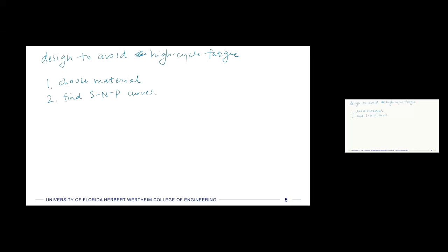And then you start thinking about your component. And if you don't have fully reversed, zero mean stress loading, then you have to compensate for that non-zero mean stress.